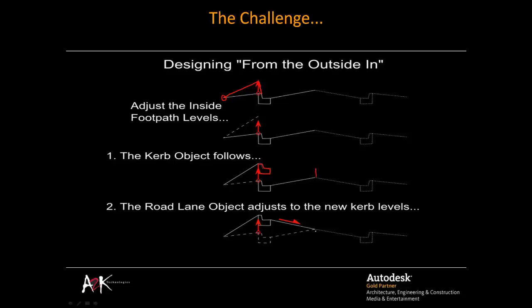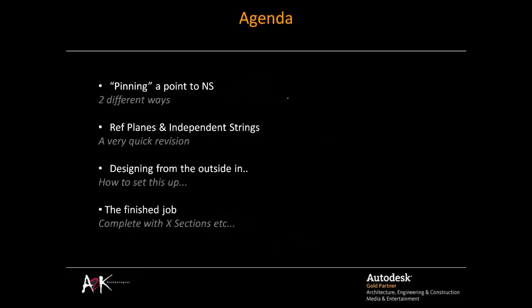What we then do is adjust our center line elevation. So I'll show it on the last section here. Say I lower my center line elevation. When that happens, it basically stretches the road down like this to match. So we use a bunch of constraints to work the system that way. As long as you understand that this is what we're aiming towards, the webcast will make lots of sense.